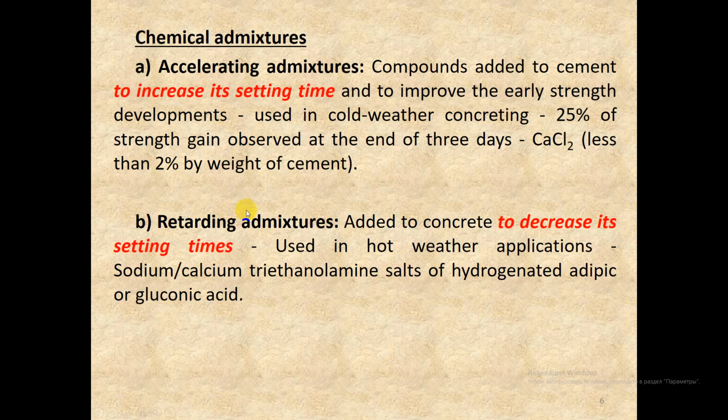Retarding admixture, added to concrete to increase its setting time. Used in hot weather applications. Examples are sodium or calcium salts of triethanolamine, hydroxylated adipic or gluconic acid.